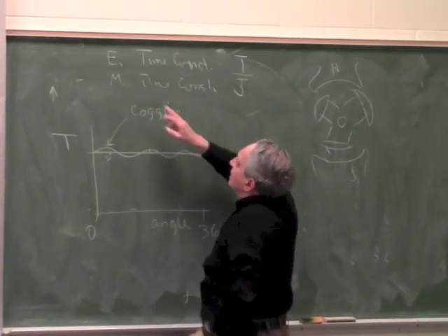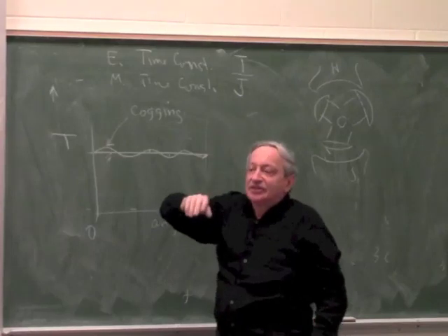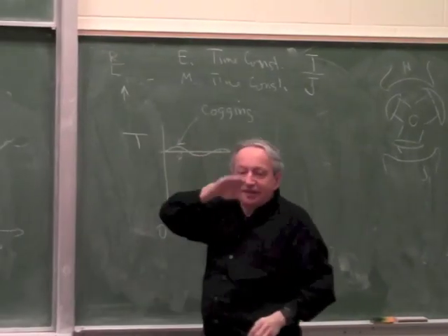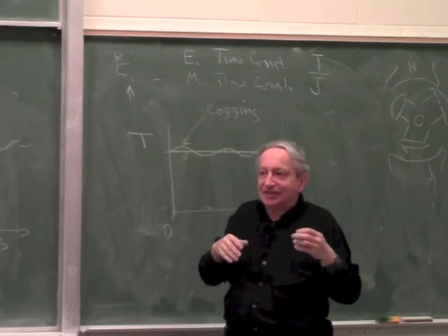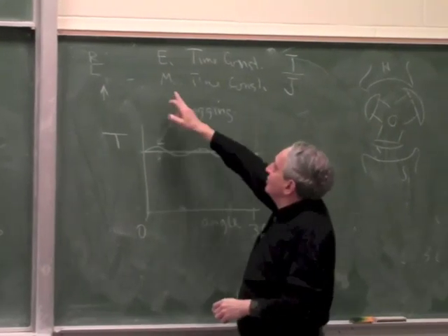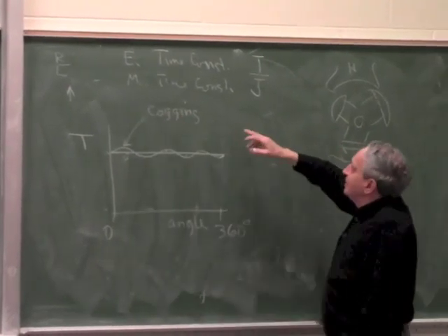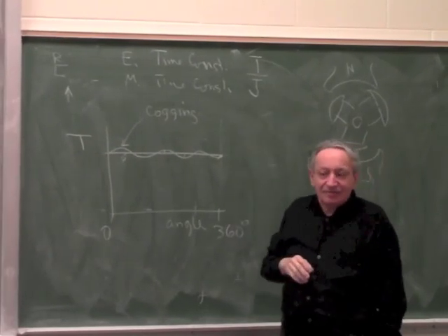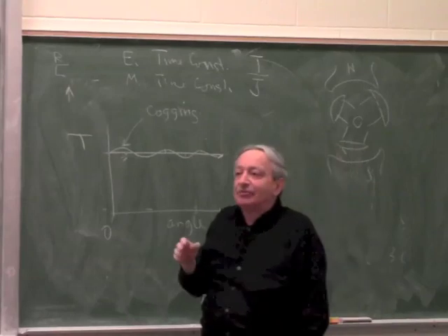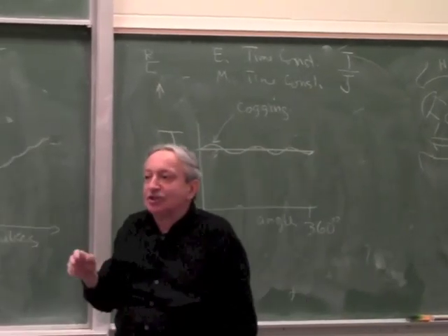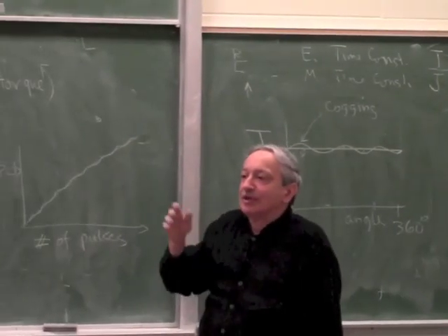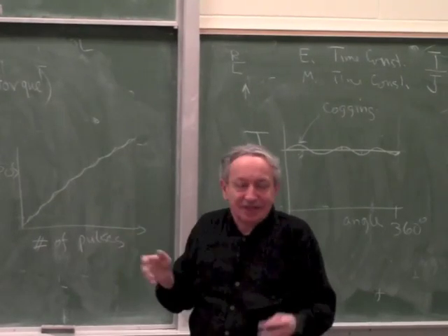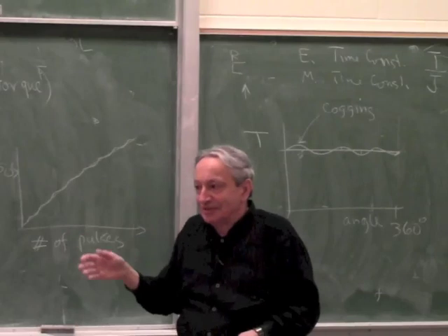So electrical time constant just means the R over L, how fast the current can rise, limited by the inductance. And mechanical time constant is basically dependent on torque to inertia. Mechanical time constant means in how many milliseconds it will reach 1 minus 1 over e, like 67% of speed. Just like time constant is defined in a capacitor, right?